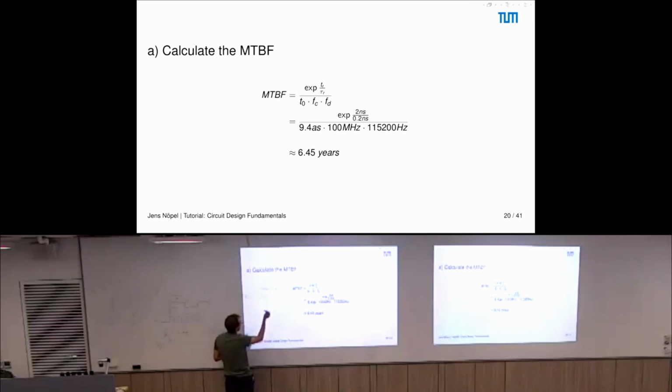So you need to sample that. What the system that is receiving the data over UART needs to do is sample the data with a certain frequency, right? And see whether it is 1 or it is 0.